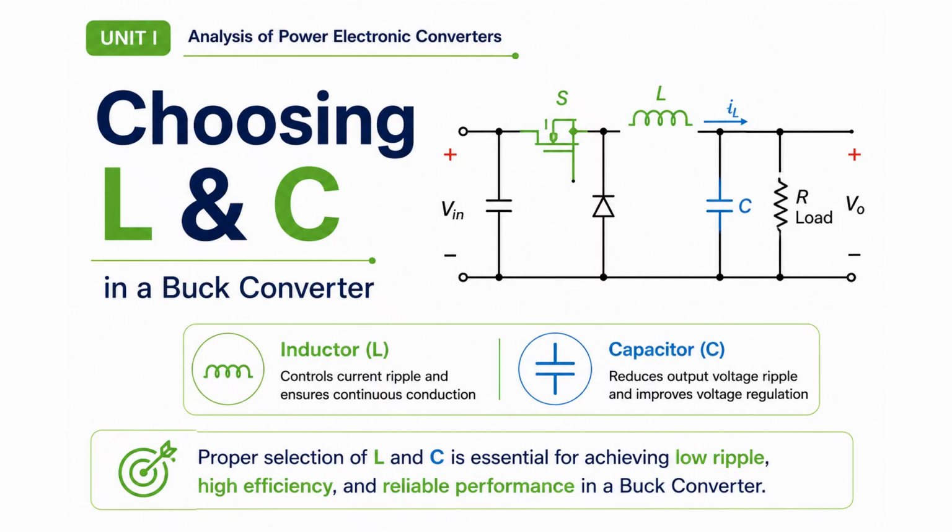When we learned power electronics, we studied the circuit diagram with only the switch and diode, but it is not actually simply a switch and a diode. Inductor and capacitor are responsible for making the converter useful. The inductor stores energy whenever the switch is on and releases the stored energy during the turn off interval.